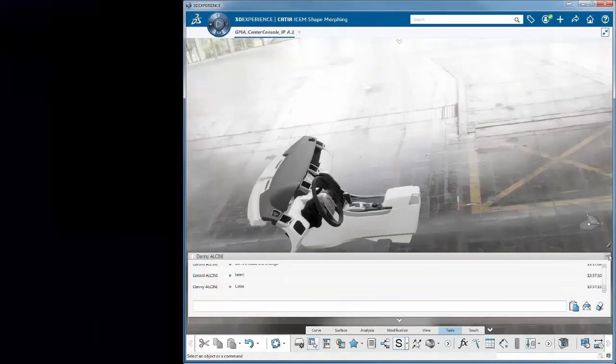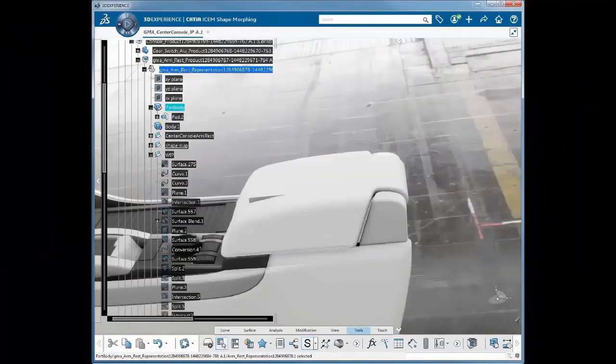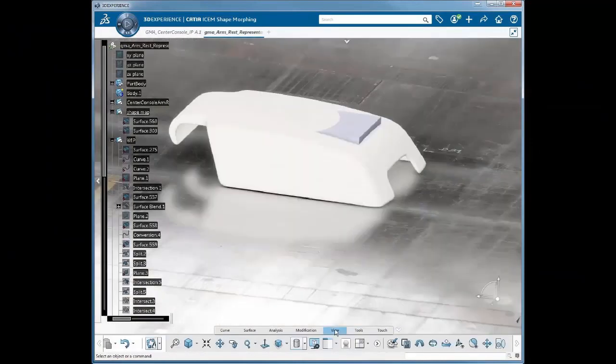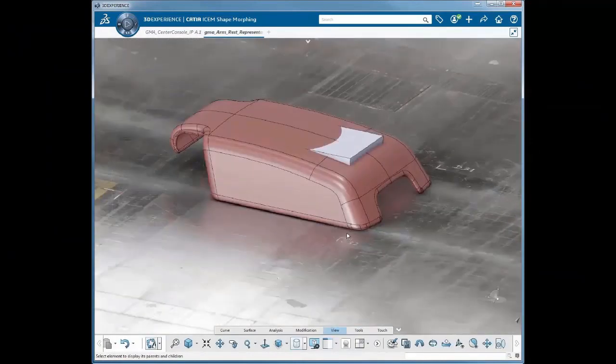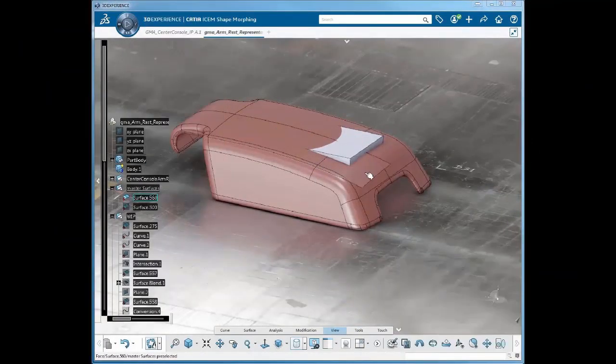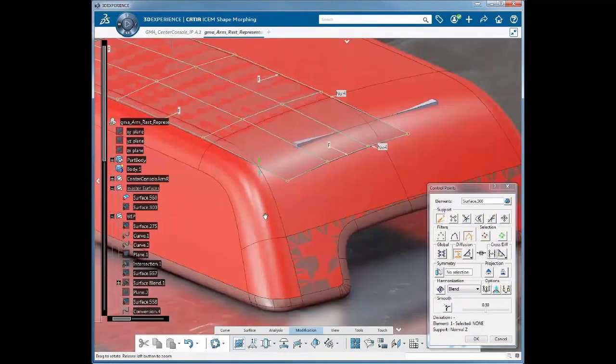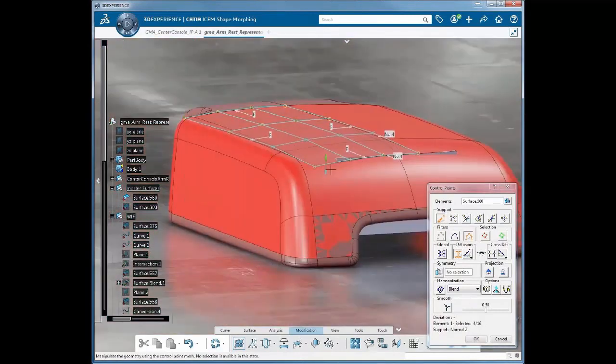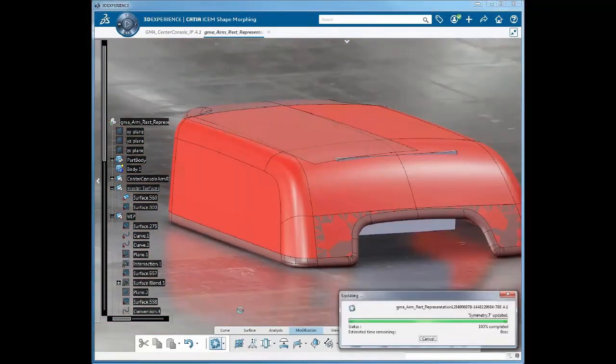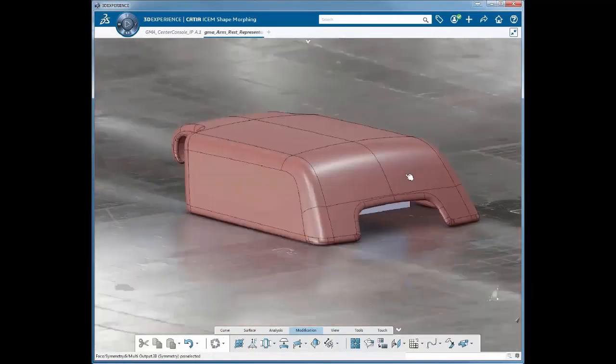And so now the surface designer is opening up that part in a new window, and we're going into CATIA ISOM, and this is an explicit surface here that we're manipulating control points on, but you see all the other surfaces are updating because those were created parametrically, just basically with the history. It's very simple to do with those blends and fillets, and it's updated.